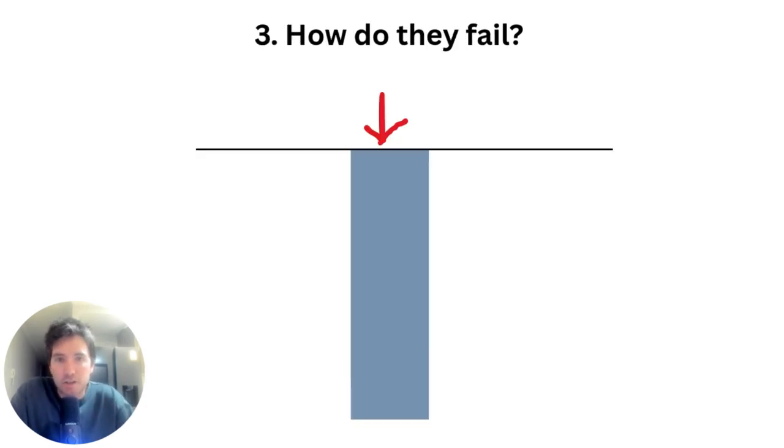So, like anything in structural design, we have to have an appreciation of how elements can fail. Foundations, including piles, can fail in three main ways. Firstly, the ground fails. So you might exceed the bearing capacity and the pile itself is intact, but the ground has failed.